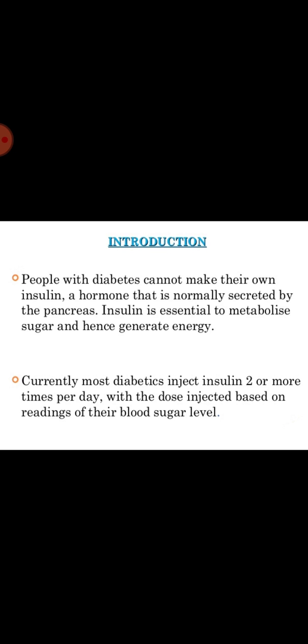The second category is peristaltic pumps. These pumps squeeze a flexible bag or tube to produce movement of the liquid inside the compressed container. Linear peristaltic pumps have a row of fingers that compress the tube in a wave-like motion, squeezing out the liquid as the wave propagates. The often used rotary peristaltic pumps use a rotor that pushes rollers against a tube along a semicircular path. These pumps have the advantage that the fluid doesn't come into contact with the pump, avoiding contamination. If true volumetric pumps are required, however, special tubing must be used.